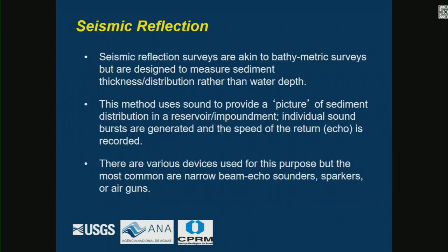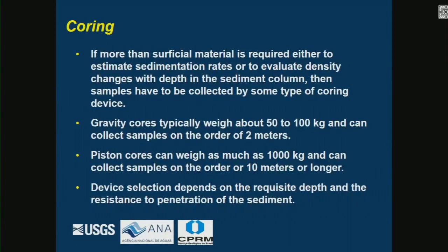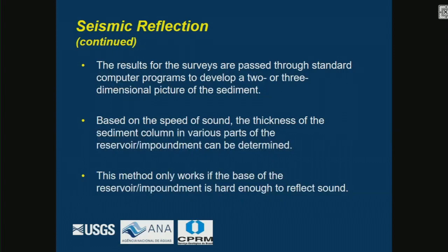So you get the original bottom, and the top of the softer sediment that's been deposited. This method works only if the base of the reservoir impoundment is hard enough to reflect sound, which in most cases it would be.